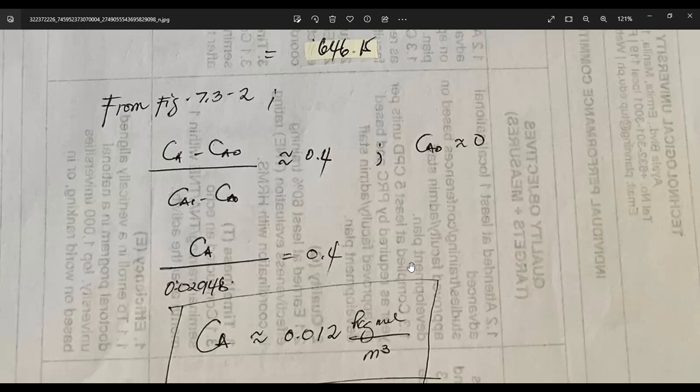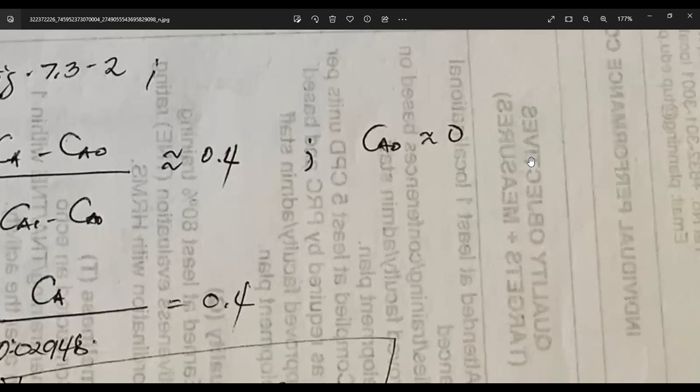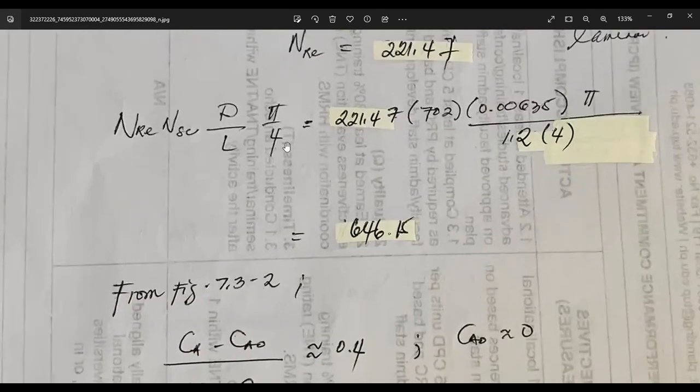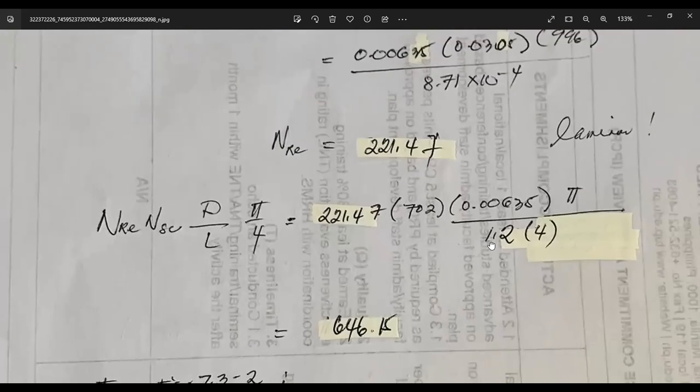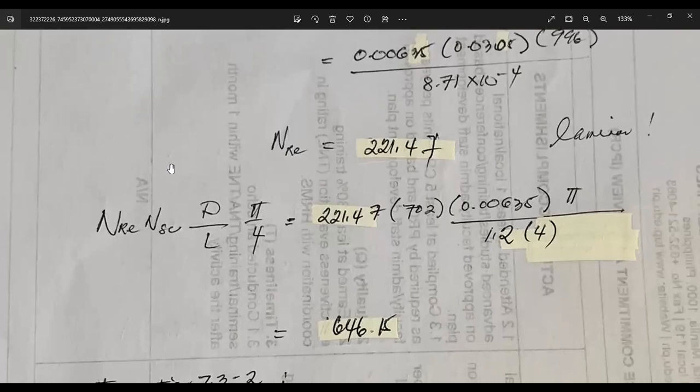But maybe, for most instances, that's what we use. Also, the flow is laminar, so not so much eddies are formed if it's laminar, so the shape of your fluid inside will not be parabolic. That is why it is rod-like. The flow is laminar, and this formula is used for laminar flow. So if you ask what we will do if it's turbulent, you cannot use this particular formula anymore.